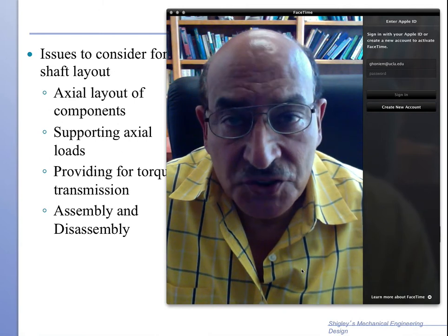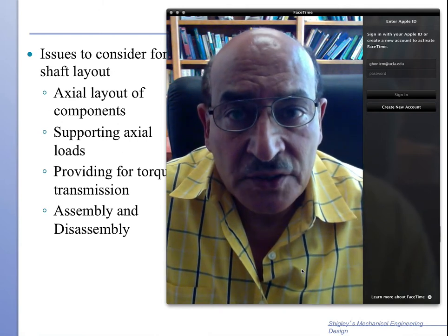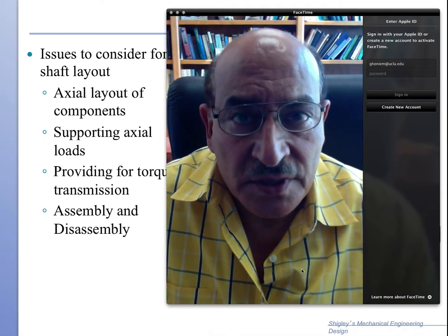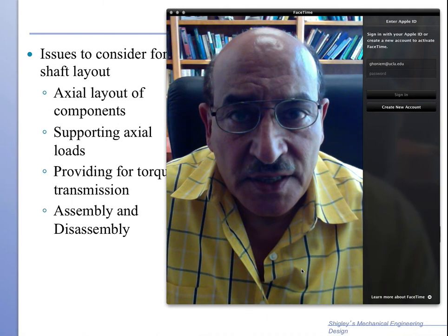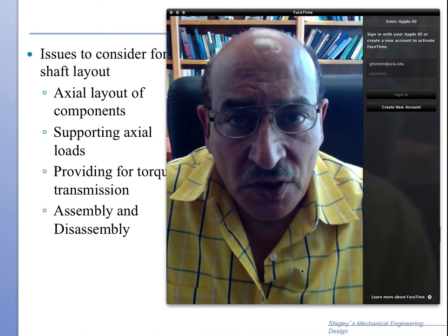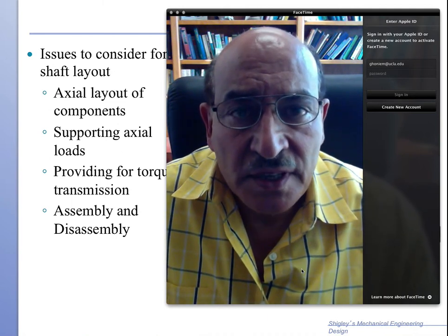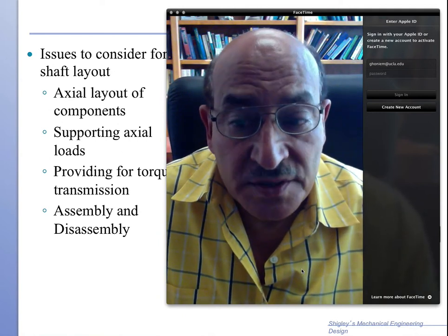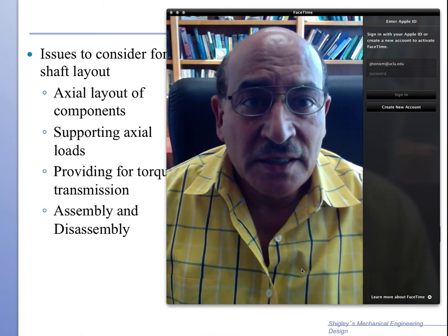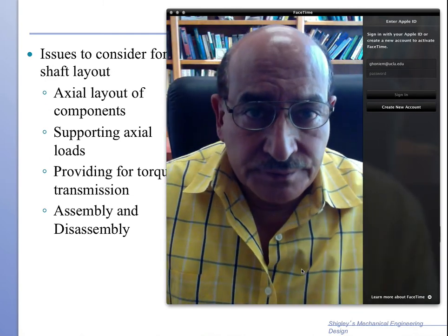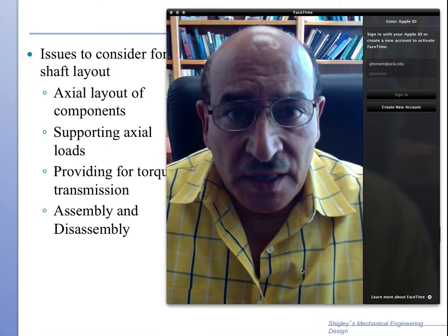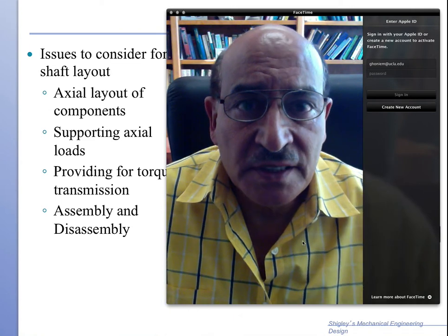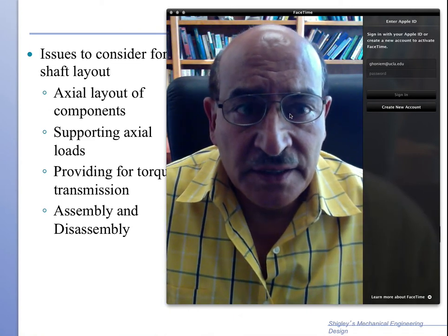In addition, to transmit the torque we have to use either gears or pulleys or similar devices, and in such a case there's always going to be a transverse force that must also be reacted at support points. So it becomes a kind of global design issue that must consider all of these cases, in addition to ease of assembly and disassembly.